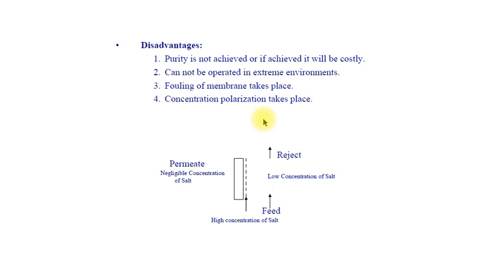In concentration polarization, the salt will still be soluble in the water, but the concentration of salt will be higher. Like here, if the salt concentration is 500 ppm, here it might be 2000 ppm at the surface of the membrane, and then it will start to diffuse in the opposite direction towards the 500 ppm salt. So you will still get the flux, you will get the water.